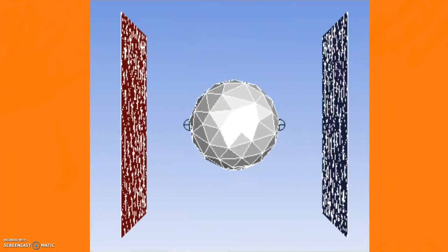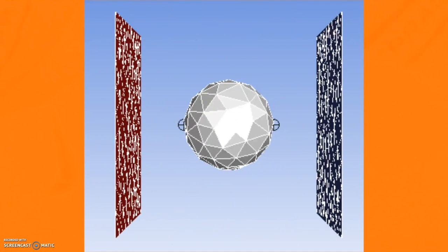The absolute pressure was measured at a point on the front of the golf ball, facing the inlet, and at a point on the back of the golf ball, facing the outlet. The simulation was run for exactly 100 iterations per golf ball, and the measurements of pressure at that final iteration were used in our analysis.